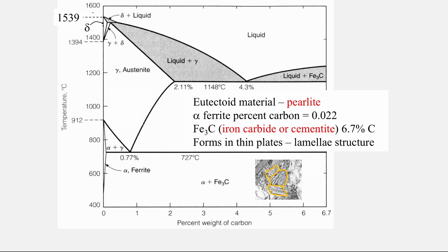So that's your introduction to the steel phase diagram. We've said steel sits at about 0.15 to 0.3% carbon, so much lower than this plot goes to, or this graph goes to. But it's very important that we understand the austenite and the low temperature ferrite possibilities because it will affect the strength of our steel.